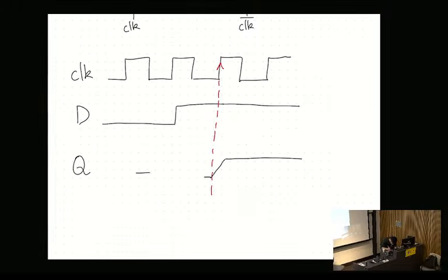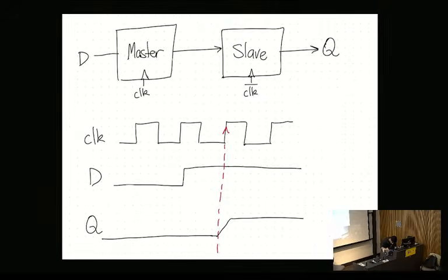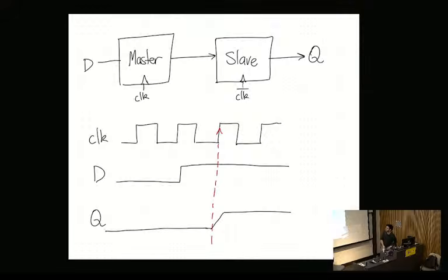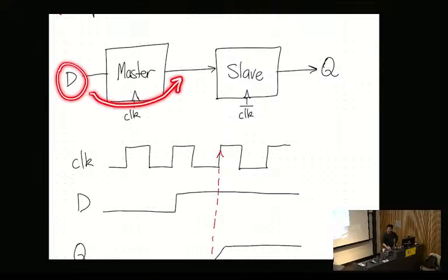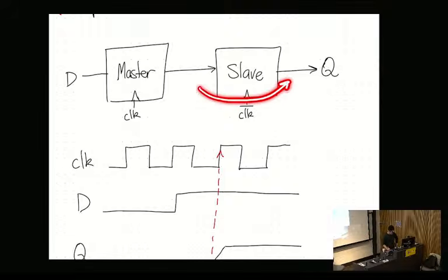Sorry, there we go. Okay. Now, the one thing to emphasize with this circuit is this is ideally what it looks like. So I've drawn it without any violations, but often an assumption we make is that the master and the slave are infinitely quick. But in reality, they take time to process the signals. So the master, the first thing that needs to happen is that the signal D needs to travel across the master. Now that might have some propagation delay of say 10 nanoseconds. Then it needs to process through the slave, and that might have its own intrinsic propagation delay.